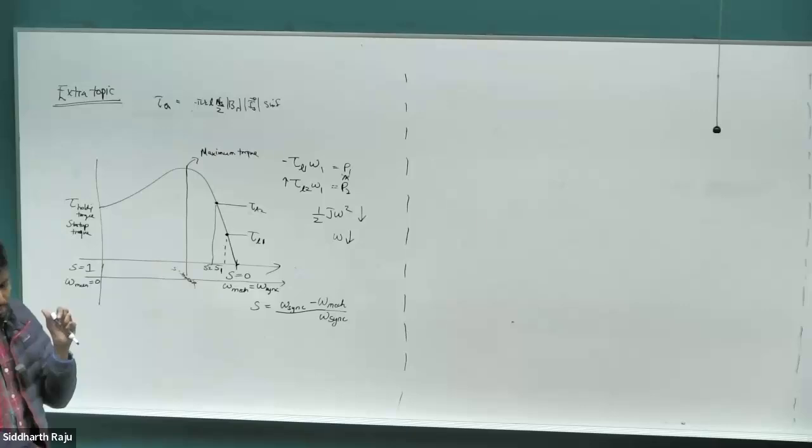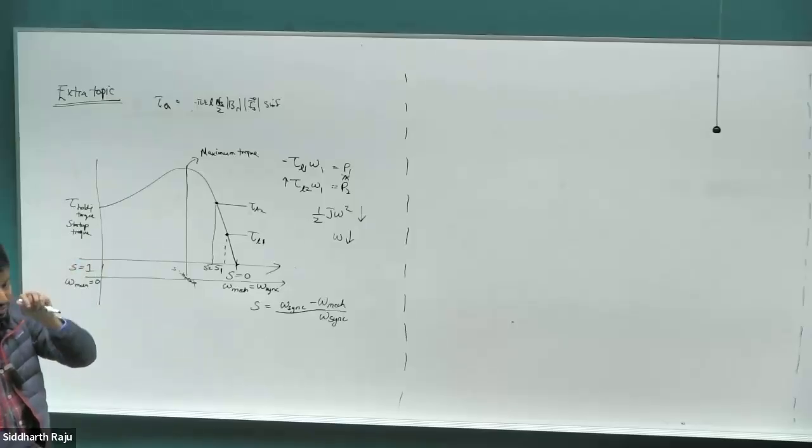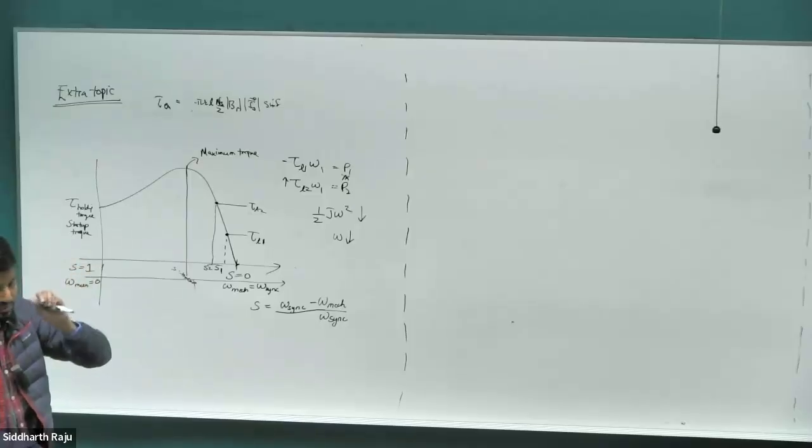But in the case of a synchronous motor, the speed was always synchronous speed. Only the angle between the rotor and the stator magnetic field, the stator current induced magnetic field B_s and the rotor magnetic field B_r, started to vary for a fixed current.